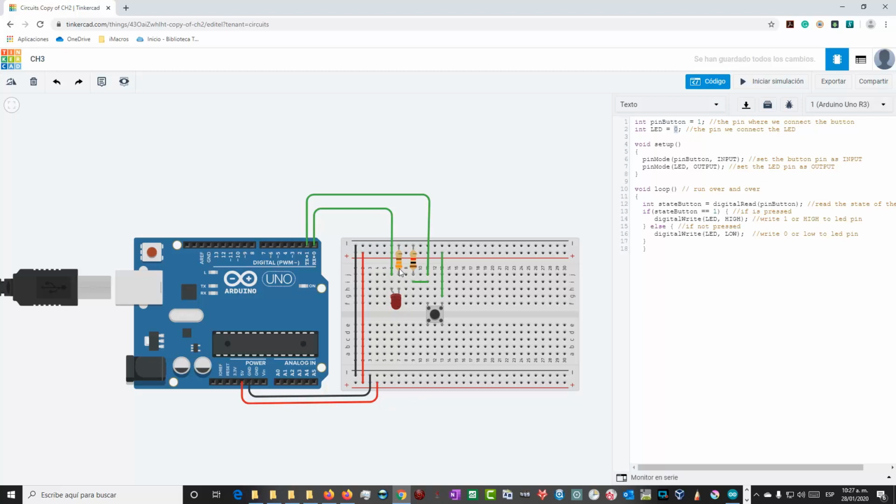So this resistance is used to control the current in this little circuit. Actually, it's to control the current in the LED. Yes, so you know, you have the skills, you have the knowledge to calculate the value for this resistance. Actually, it's 313 ohms, but I am sure that you can calculate this value and check that this is the proper value for this resistance.